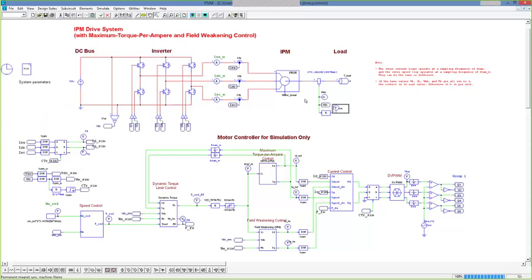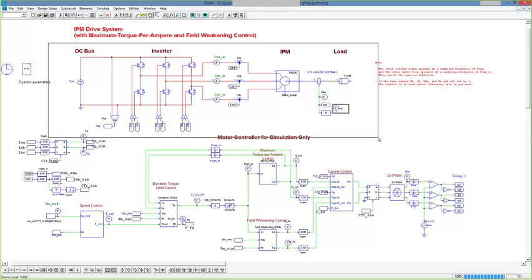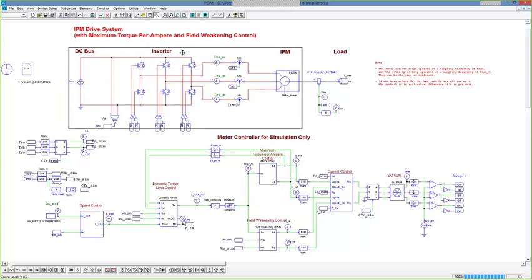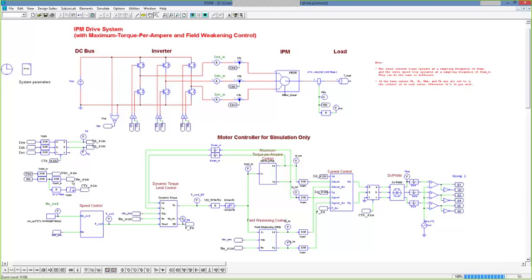One thing that I would like to highlight about PSim is there's 2 basic signals in PSim. If you can see, the top level circuit here has red traces. This is a power schematic. And you need to interface between the power schematic and the control schematic, which is defined with green traces, through these current sensing blocks, or this voltage sensor, which will convert power to control, the current sensor, power to control, and these on-off switches.